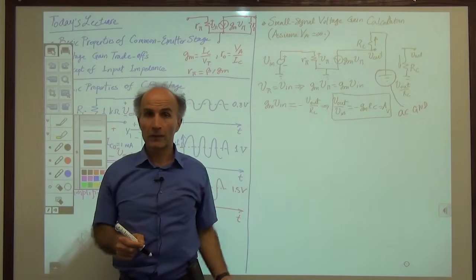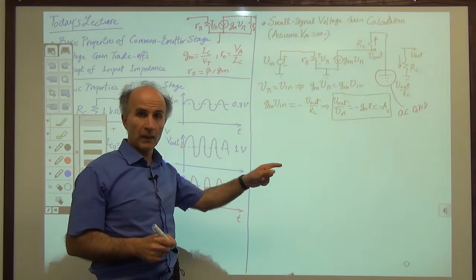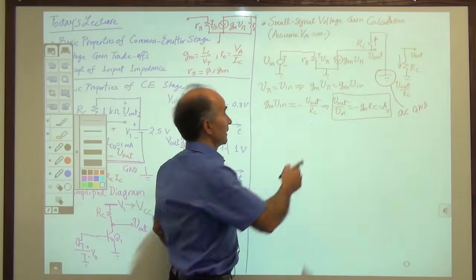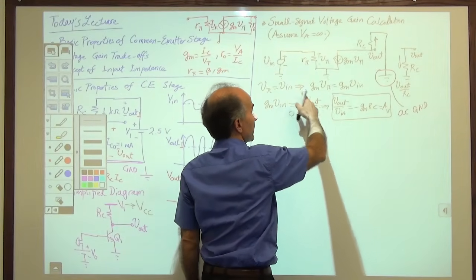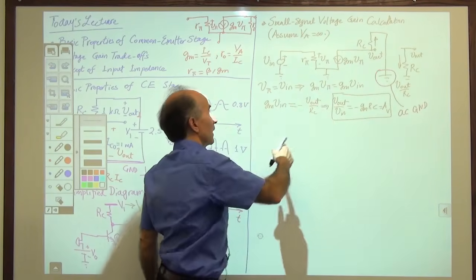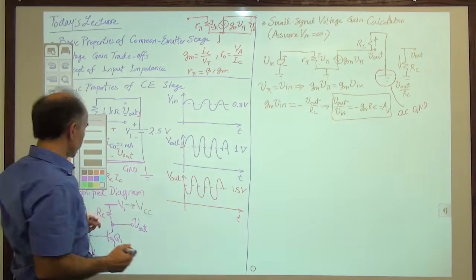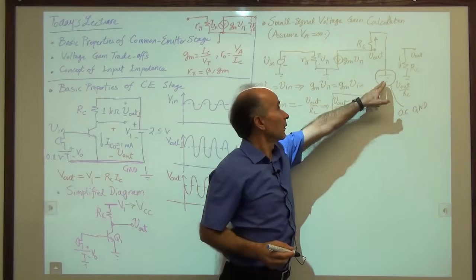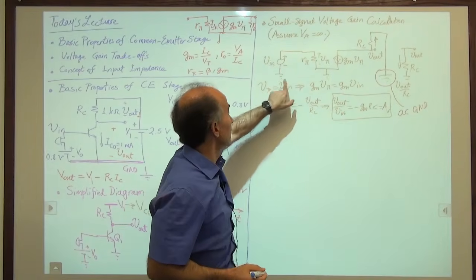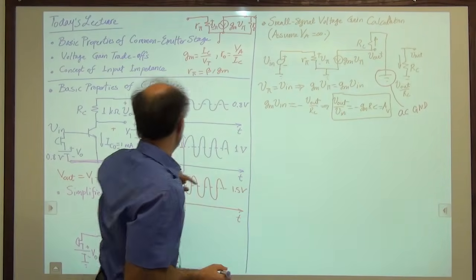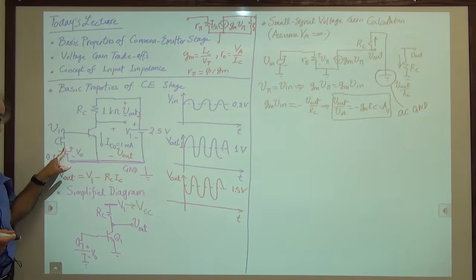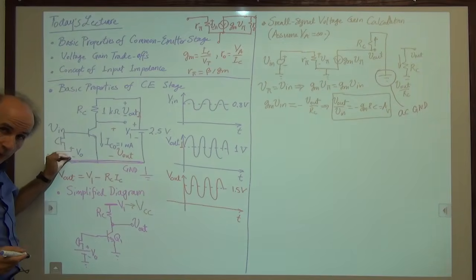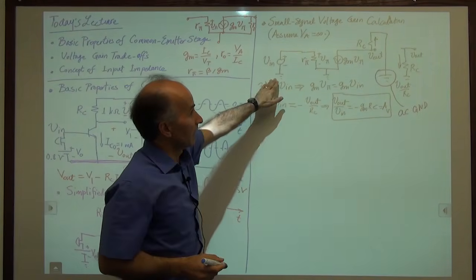Okay? So in a small signal model, we have only grounds, and they're all AC grounds, but some of them came from different places, right? So this is still AC ground, this is also AC ground, except that this ground originally was a ground, as you can see here, but that ground was not. Similarly here, this is also an AC ground because originally the bottom terminal of the microphone was not connected to ground. But because this battery was forced to go to 0, we ended up with a ground here as well.